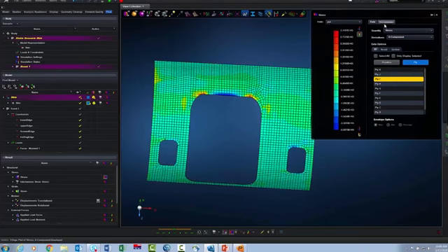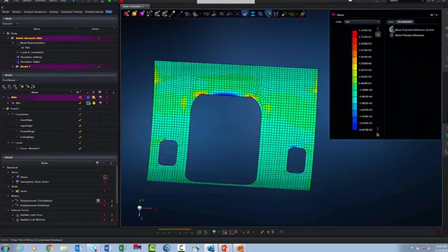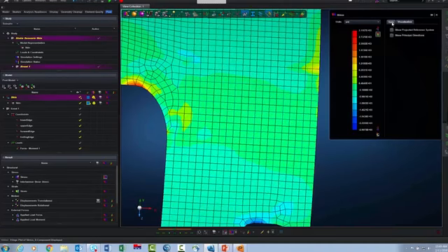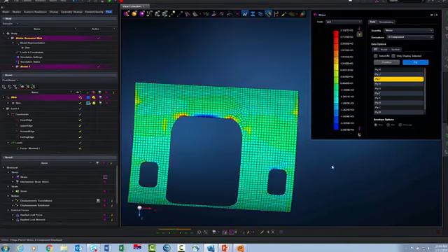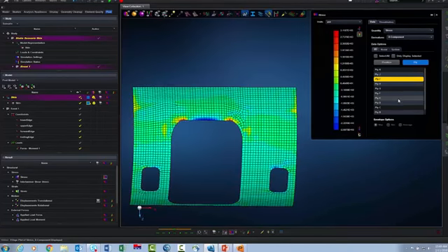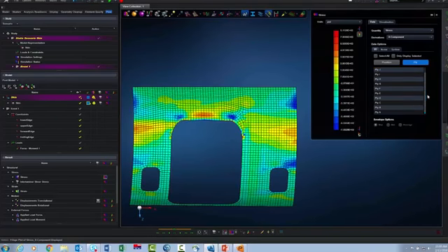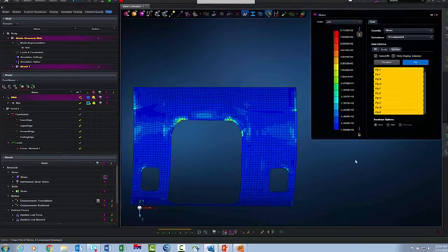If I need to remind myself of what the material orientations are, I can quickly do that as well. So, you know, I don't have to go very far to actually see what the material orientation for this ply is. I can also come in and select maybe all of the plies, okay, and I'm looking at sigma x, which would be the fiber stress here, and we'll turn on some hot spots, okay?